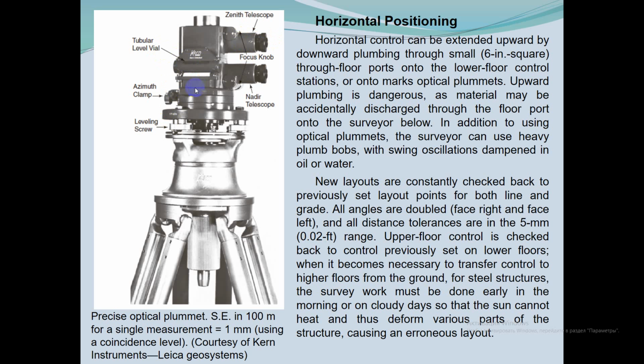Upward plumbing is dangerous, as material may be accidentally discharged through the floor port onto the surveyor below. In addition to using an optical plumb, the surveyor can use a heavy plumb bob. You know what a plumb bob is, with swing oscillations dampened in oil or water.